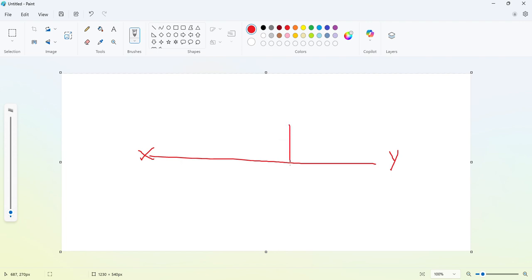Suppose this is a projection, point A is above HP and in front of VP, so this is going to be A and A dash. Now we are considering the right view, and the projection will appear on the LPP, the left projection plane. So on the left side of this projection I'm going to draw a reference line. This line will be X1 Y1, and it should be perpendicular to this XY line. This distance between these two can be given in the question.